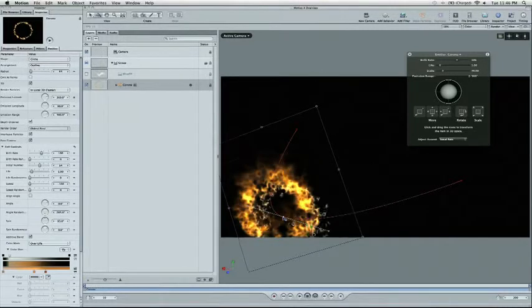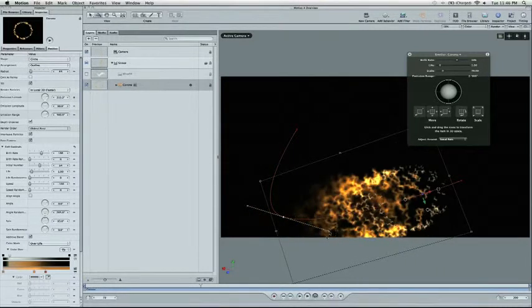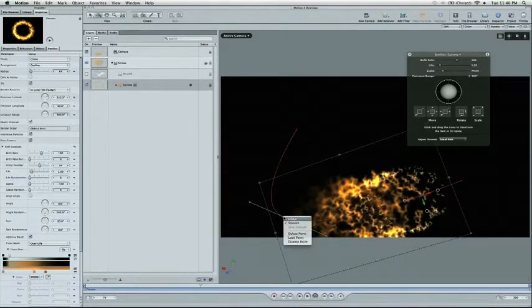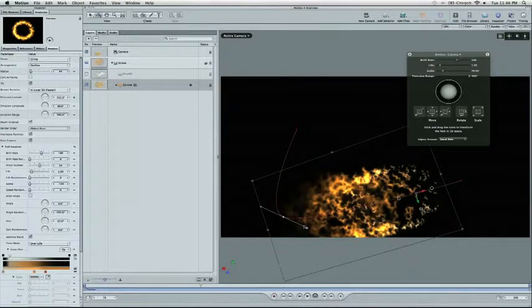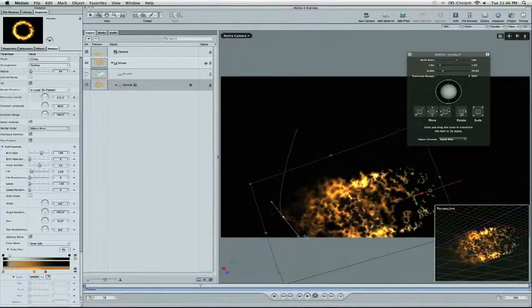Now you see the little smoothing handles here. I could change that and go into linear by right clicking, and it's going to be a solid edge. But I like the smooth. It gives us these Bezier handles so I can make this nice.